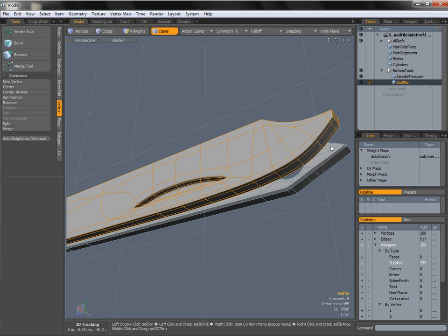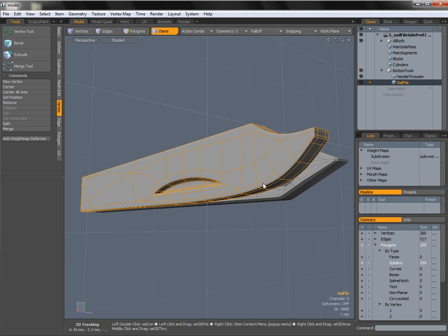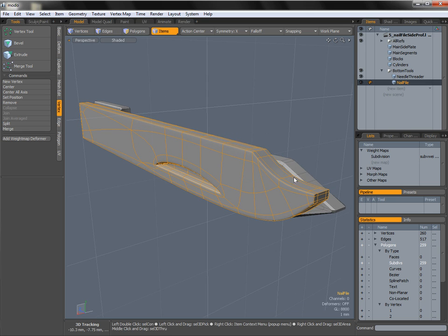We had this bottom curve here, and we created it in subdivision surface mode by adding in about 7 or 8 different verts. If we weren't using subdivision surface mode, to get this level of smoothness, to get this level of quality so that it will look this good on our final render, we would probably have to add in 24, maybe 30 edges onto this bottom curve, and to get those straight and so that they all perfectly flowed into the next one would be quite a task. The same is true obviously of this top edge here. You'd have to add in a whole bunch of extra detail if you weren't using subdivision surface.